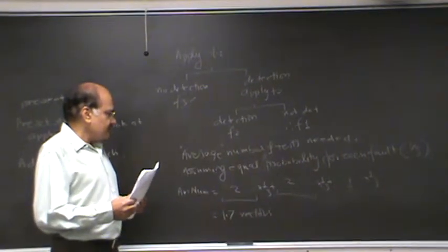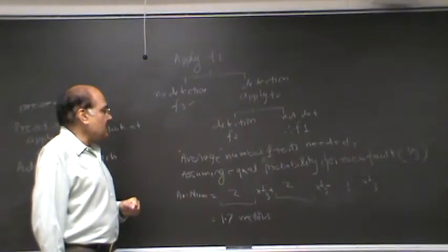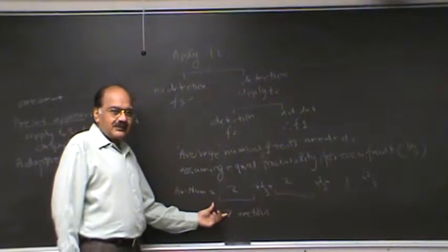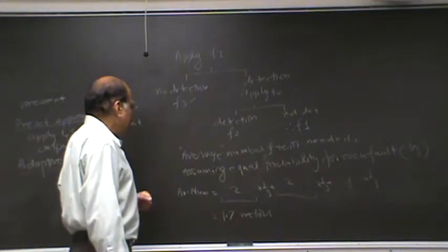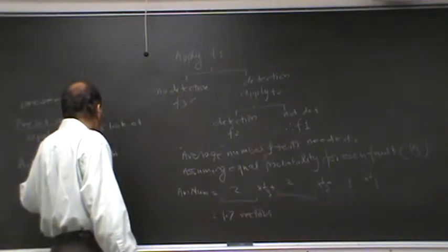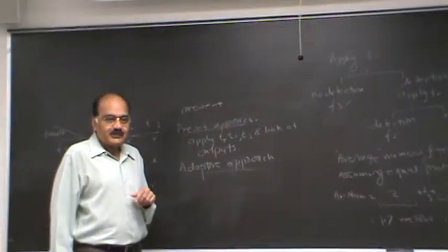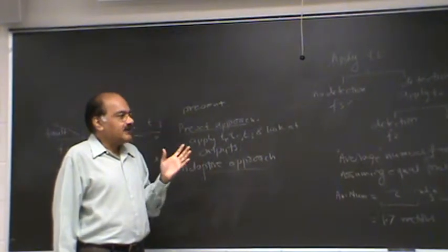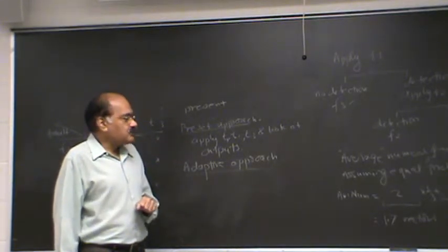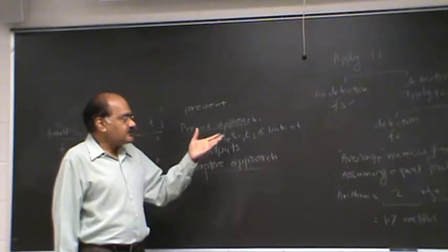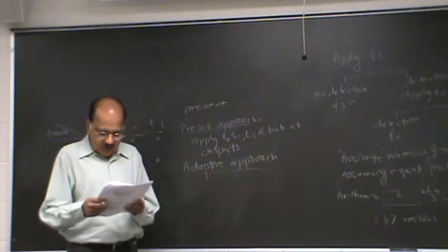the expected number. So in general, if you do adaptive testing, it's going to take sort of less than 2 vectors. That's the expected value. And as opposed to a preset case, when you were applying all 3 vectors. So basic idea is that if you are prepared to use some intelligence as the process is going on, you can optimize the performance of your fault distinction problem.